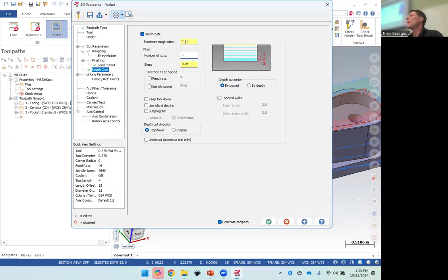My rough step would be my full pocket depth, and then 1 10 thou finish pass will come back and clean up the floor and clean up the walls. Does that make sense? Are those the same sorts doing floor? It'll do the floor, and then the last one it does the wall.